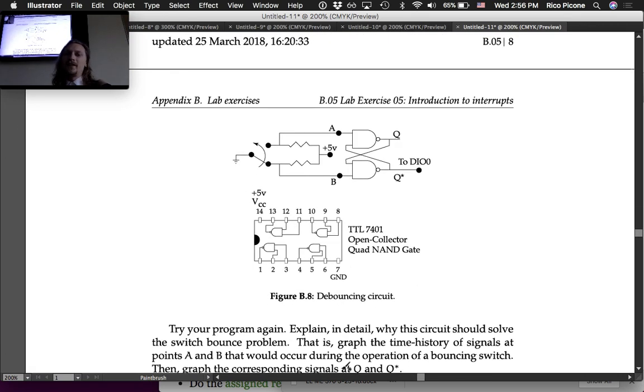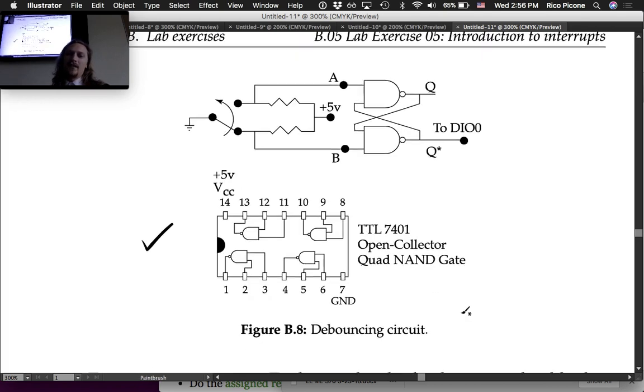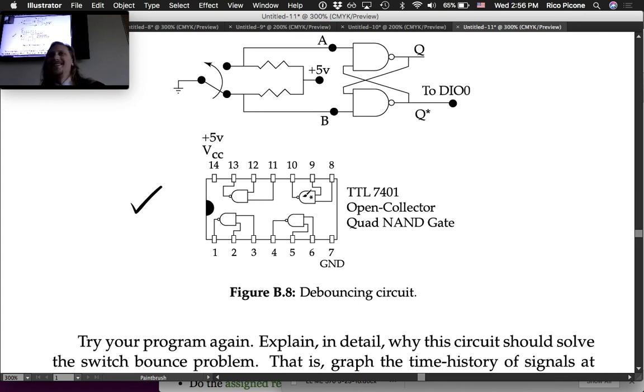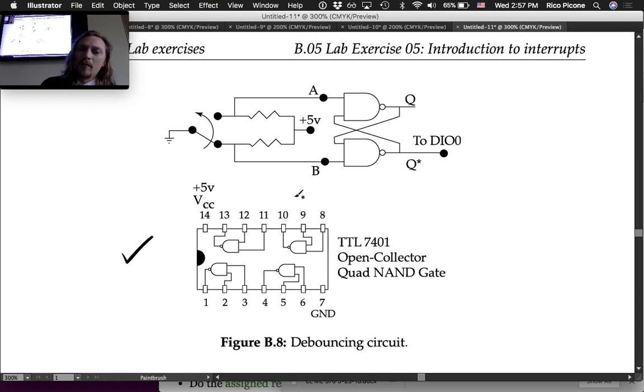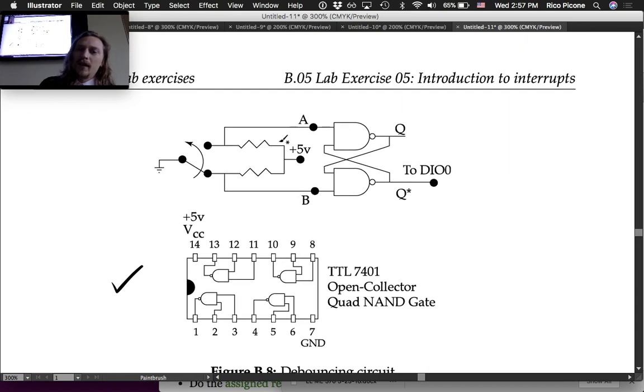In the other case, you're going to use this chip here, and it's got 4 of these NAND gates. Right? And now we've talked about NAND gates, so now we can talk about how this thing works. So we've got 4. We don't need 4. We only need 2. But we'll connect up and use any 2 of them in the form shown here. So these resistors are already on the breadboard for you, and they're already connected to 5 volts. Do specifically use the two NAND gates that they're connected up to, so you don't have to rewire that part.